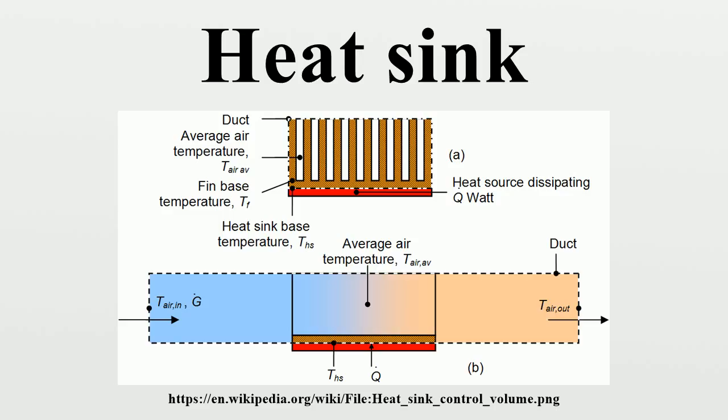A fin of a heatsink may be considered to be a flat plate with heat flowing in one end and being dissipated into the surrounding fluid as it travels to the other. As heat flows through the fin, the combination of the thermal resistance of the heat sink impeding the flow and the heat loss due to convection, the temperature of the fin and, therefore, the heat transfer to the fluid, will decrease from the base to the end of the fin. Fin efficiency is defined as the actual heat transferred by the fin, divided by the heat transfer were the fin to be isothermal.